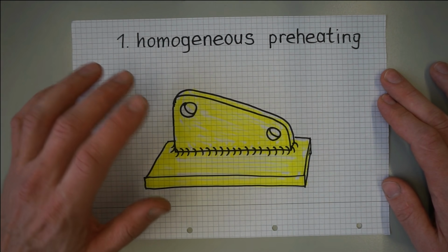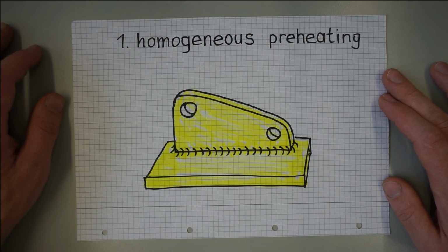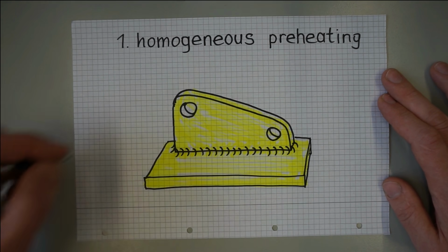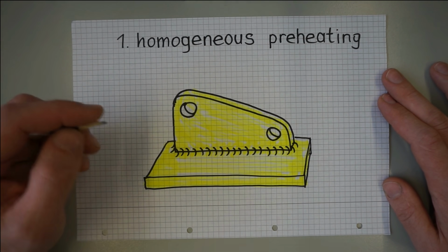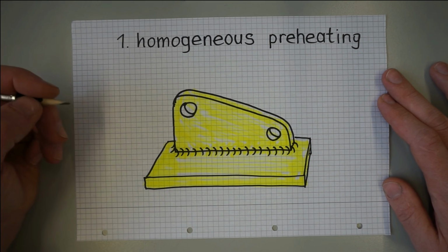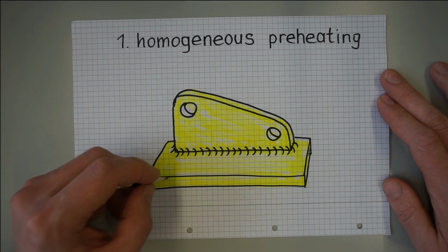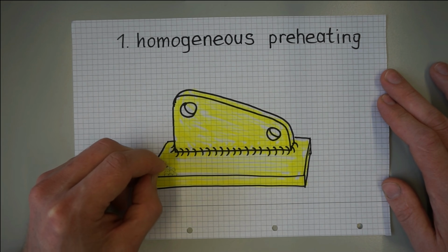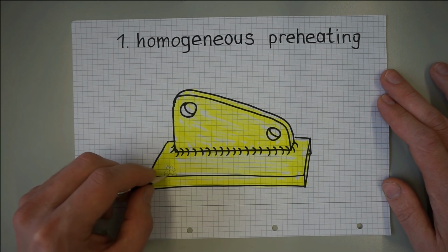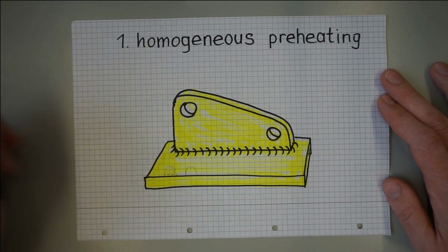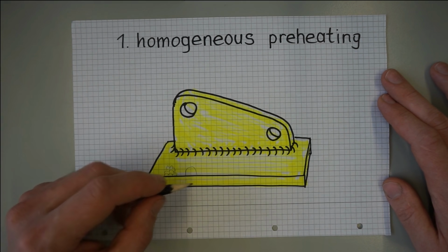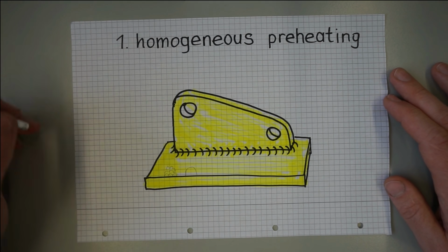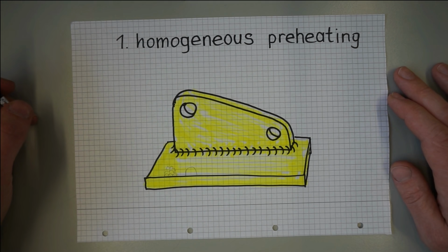So usually we don't even yet have to worry about surface scaling, for example. The workpiece's mechanical properties should not deteriorate because of preheating. This, however, takes place already when the material begins to recrystallize. That means the thousands and thousands of crystals our polycrystalline workpieces are made of start to grow on us and become larger and larger. Recrystallization occurs at much lower temperatures than the melting temperature and will diminish material strength permanently.